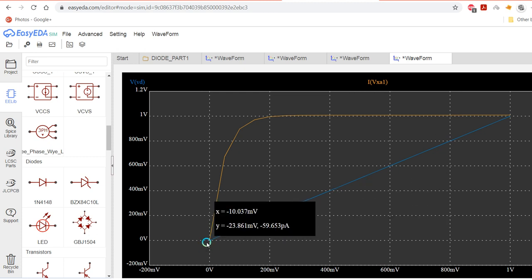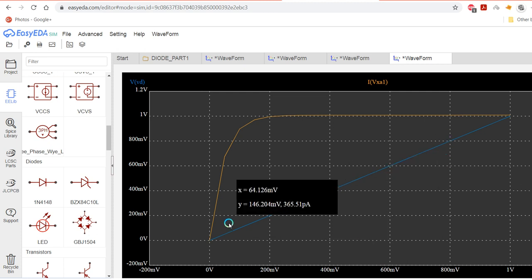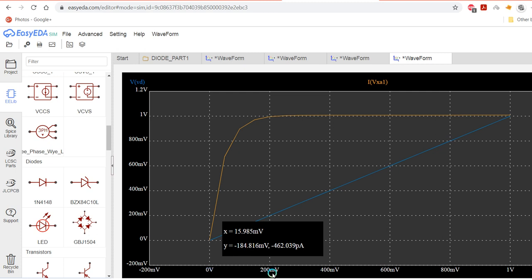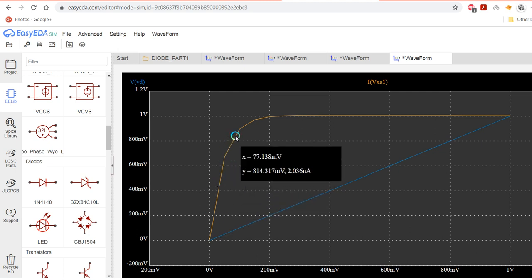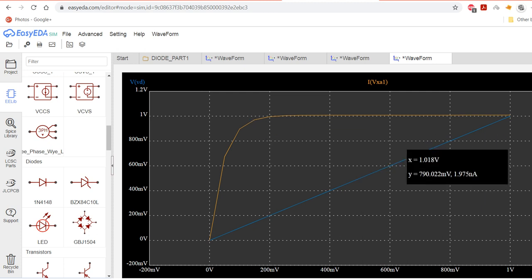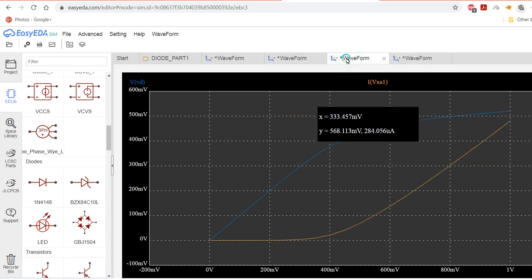Okay, so we can see here, this is the voltage across the diode VD, so forget about it. You can see that as you're changing the voltage from 0 to 1 volts in the reverse direction, your diode current is first increasing a bit, to a value of 2.5 nanoamperes. Now automatically the current range has changed from the milliamps, which was in the forward biased conditions,